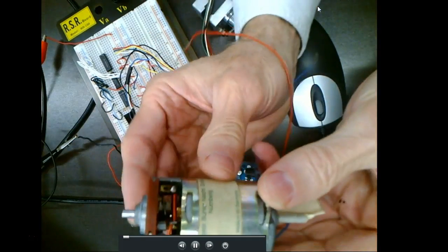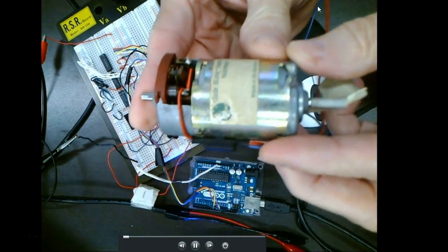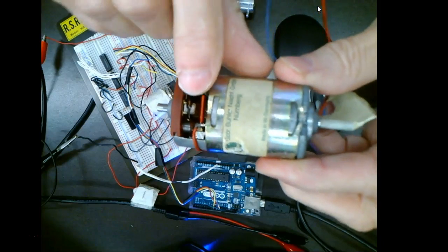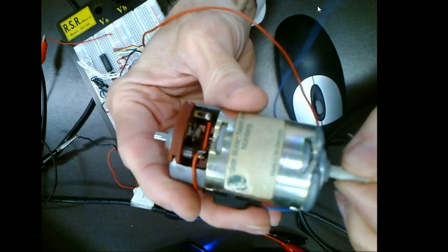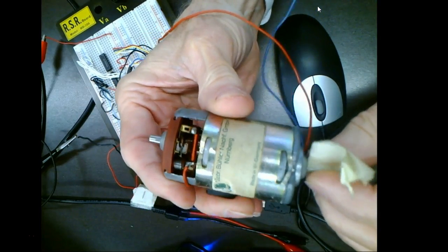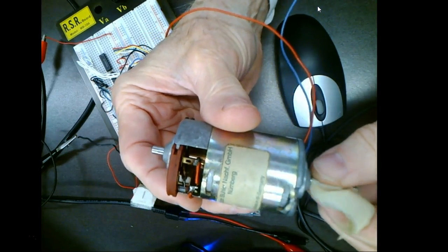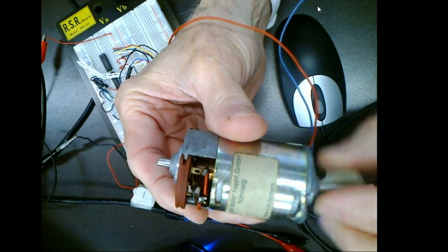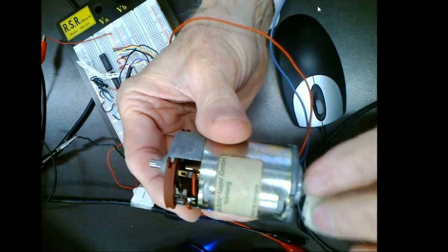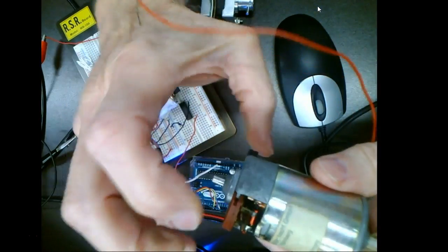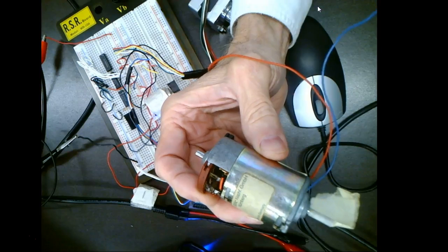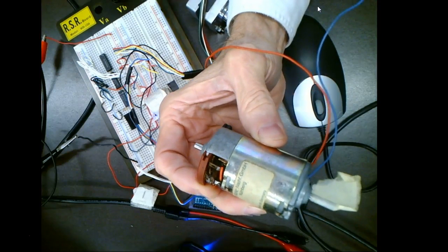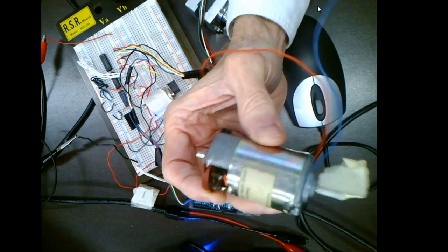So this is the DC motor, and I like this because you can actually look at it. There's the brush right there. When you rotate it and spin it with your finger, you can actually see the commutator make the switch. It's going to be hard to see right here. I don't know if y'all can see the little black line switching there. What's happening is that when this spins, it constantly switches the magnetic field on the rotor, which causes the motor to rotate.